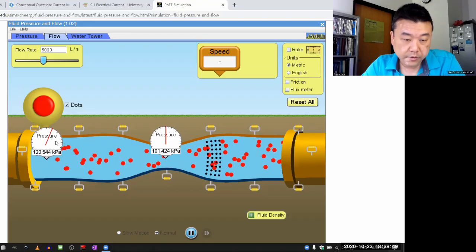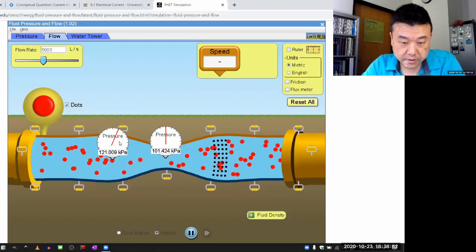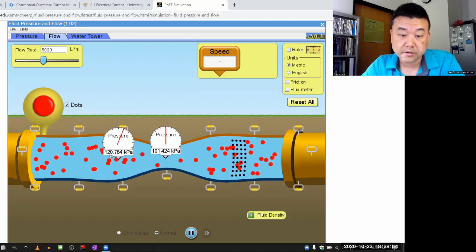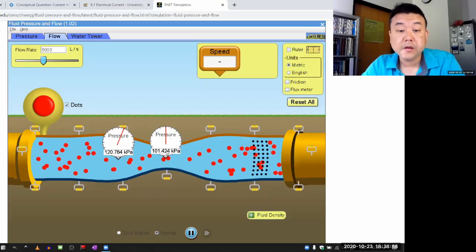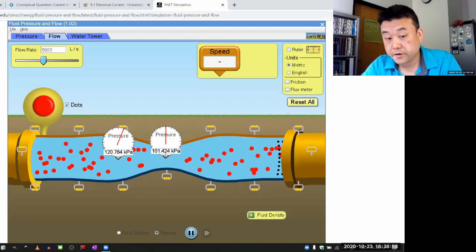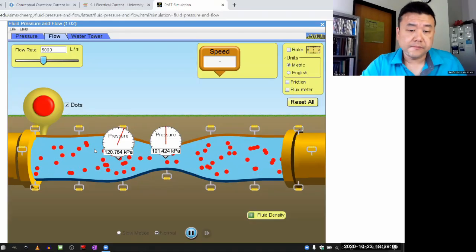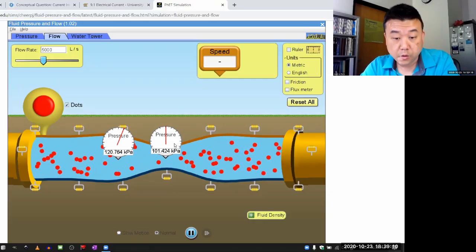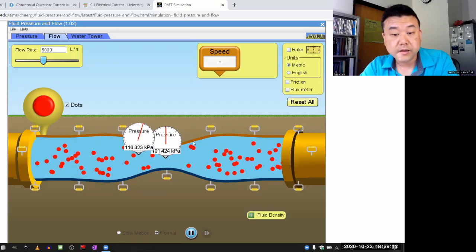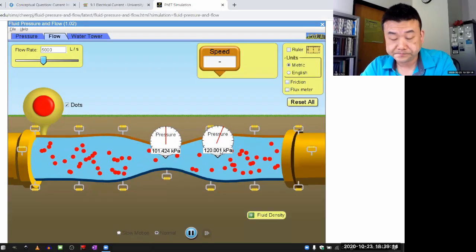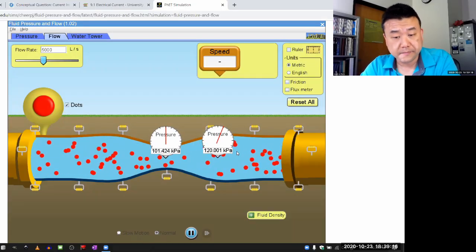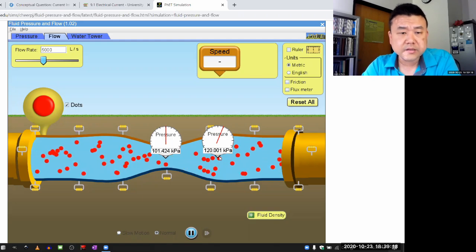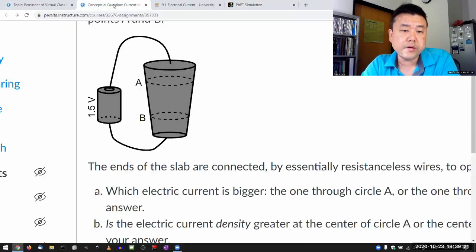This fluid flowing from the midpoint to here, there's a distinct pressure difference. It's this pressure difference that pushes the water element through, so that it's faster here. And once it's through this portion, the pressure difference is the other way, and that serves to slow them down.